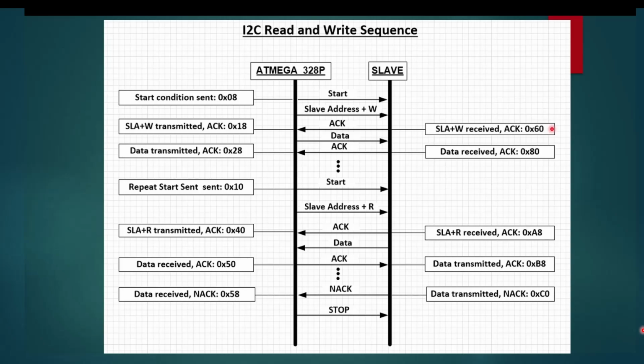After getting that command, the slave will start monitoring the status register again, and every time it gets a status code 80, it knows that it had gotten new data and has acknowledged it. So it will go and get the data and then go back to continue monitoring the status register.